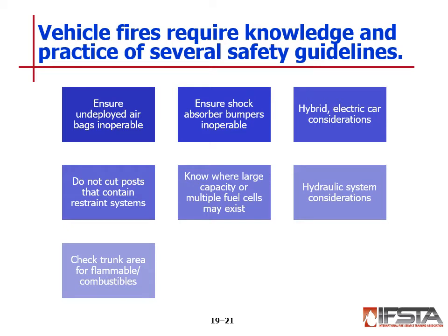Remember that undeployed airbags are a danger, and you want to make sure they're deactivated. Ensure shock absorber bumpers are inoperable. Remember the hazards with hybrid electrical cars. We've talked about those, and the different types of fuels that are used on them. We don't want to cut the posts that contain any restraint systems. There are devices in there that can cause some harm.